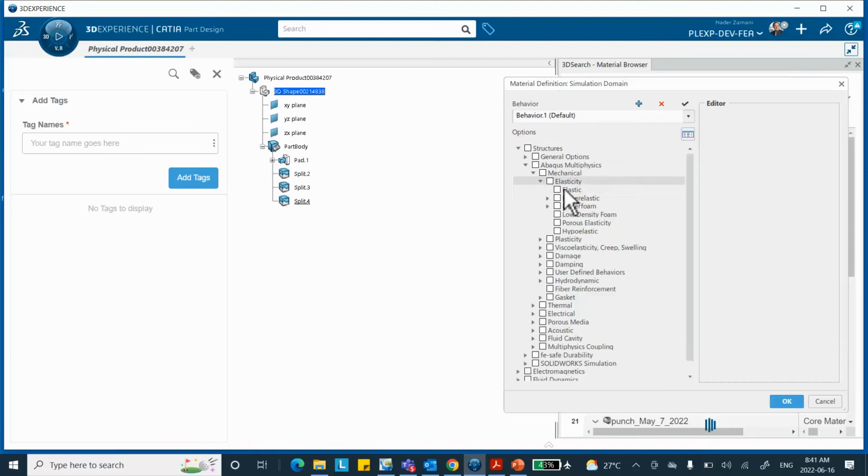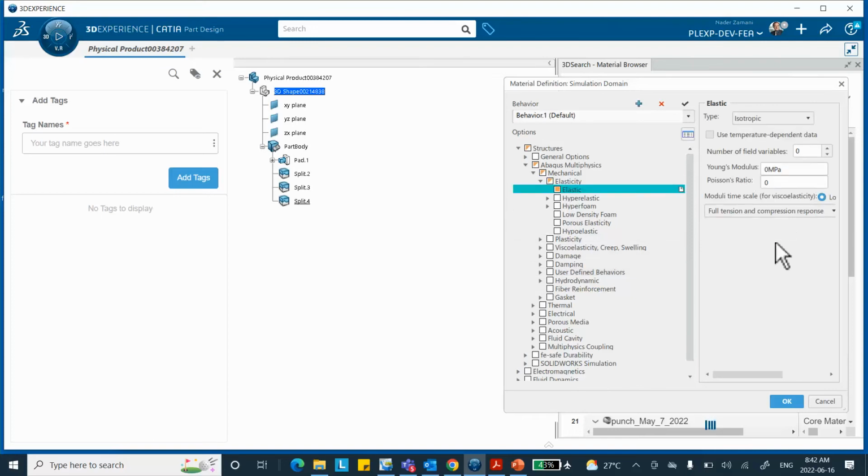elasticity. Notice that here you can do elastic, hyperelastic, plasticity, all stuff. In Catia, all you can do is linear elasticity. Hyperelasticity is when you have rubber material, gaskets and things like that, gigantic compressions and things of that type. You can't do it in Catia. You know, you can model it, but it's garbage, pure garbage. So you click on it, and it's very simple. Two numbers. For static analysis, you need two numbers. What are those two numbers? There's a whole whack of stuff here, but you need only two numbers. What are they?